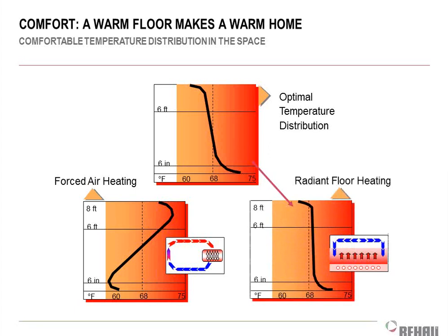Because radiant heat, as you probably know, is delivered quite a bit differently than air-based heat. Air-based systems are primarily convective heat, right? So that's air motion, using air as the heat delivery mechanism. There's also conductive heat, right, which is touching a surface, like putting your hand directly on top of an electric stove, right? That would be conductive and stupid, by the way, right? So conductive, convective, and radiant are the three main ways to transfer heat, and then the fourth would be evaporative, but that doesn't really apply in this scenario for heating.